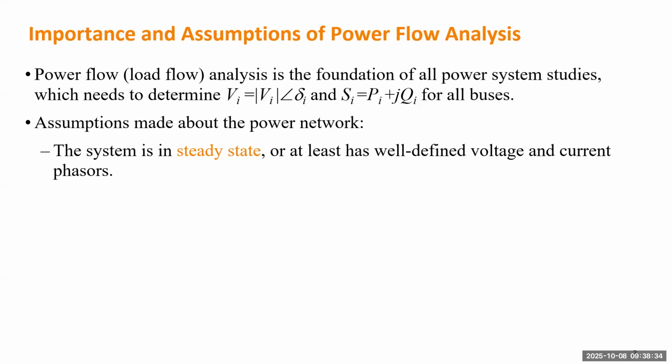But when we apply the power flow analysis to different applications, in some applications the system may not be exactly in the steady state. If it's close to the steady state, the power flow result will still be meaningful. It still represents an approximation of the system condition. If the system is perfectly in the steady state, the power flow result is completely trustable.